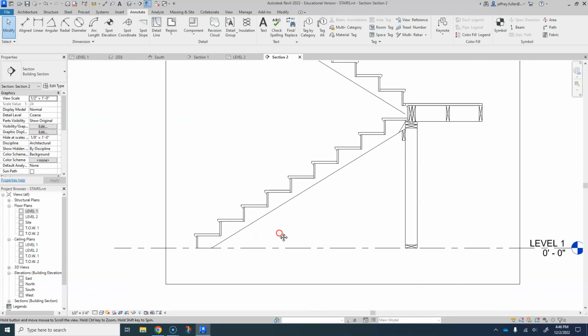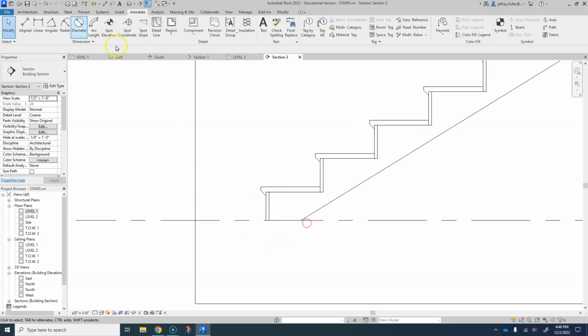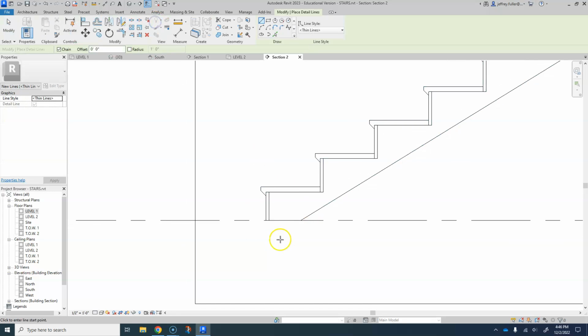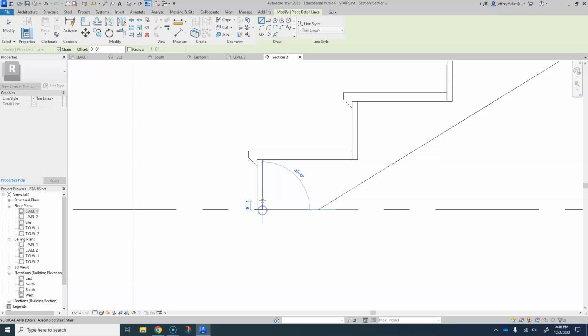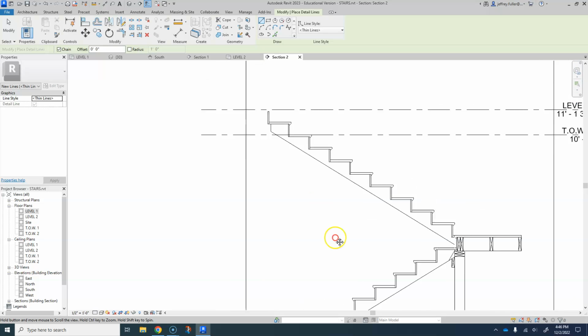Okay, and then let's see, we're going to come down here. We're going to place a nailer on the floor. We're going to make it a 2x6. Come up 1.5 inches. Draw over 5 1/2. Right there. Then put your little crosses in there. That's what everything's going to nail to at the bottom.